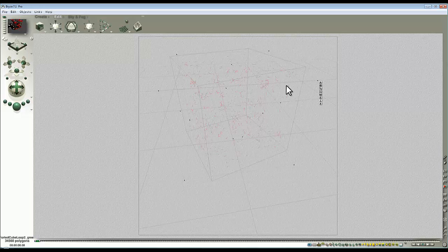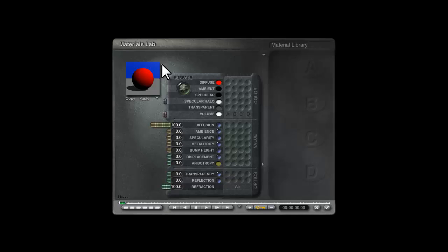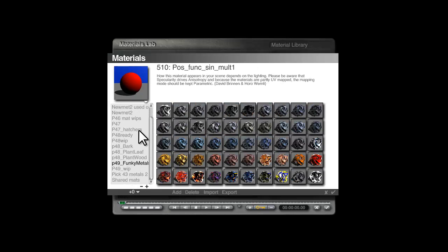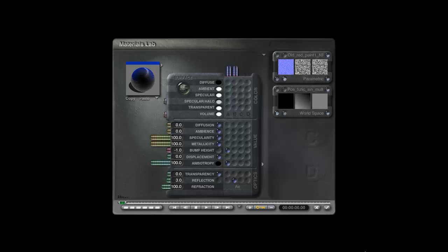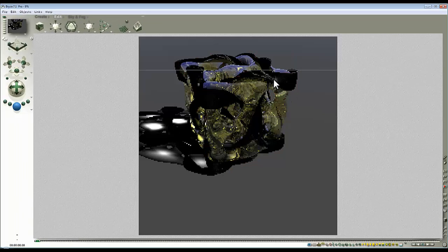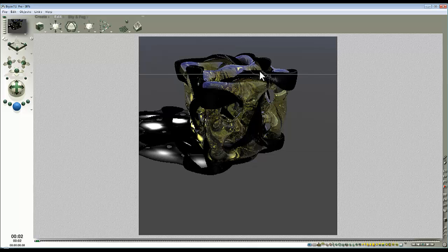These red sections, this weave, I'm going to give them a material from the funky metal set, but any material would do. It's just I wanted to promote that product, that's all. So I'm going to use this specular material with reflection. I'm going to get rid of the reflection, actually, you see, and just use the specular highlight that's being generated through the specular channel. So you can see this sort of white highlight here that's scattering across the surface, give it sort of velvety look.